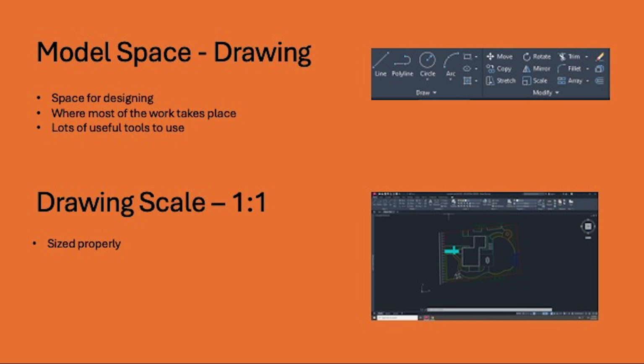Trim was useful to keep everything neat by cutting away extra lines. The copy tool was really helpful for duplicating shrubs, trees, and the three lounge chairs. The arc tool came in handy for creating the curved walkway and the rounded planting areas. Hatch was used to fill the crayon walkway at the front of the house, while the offset tool was used to create the interior walls of the house. The erase tool helped fix any errors along the way.